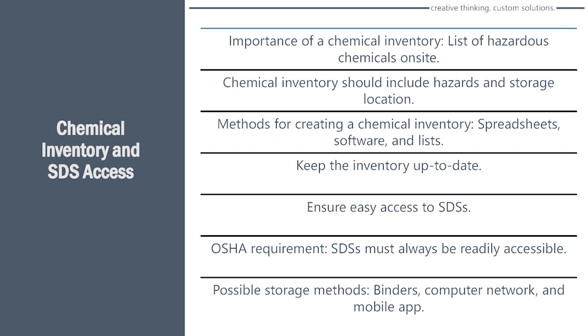Today, you've got all these other tools that are available to you. So your chemical inventory is probably maintained by some kind of existing inventory. And then when purchasing buys a new chemical, they notify someone in EHS, probably electronically, and that automatically gets added to the system. So that's a great way to manage that, and it allows you to be sure you've got what you need. The chemical inventory should include the hazards and the locations of the chemicals, which is the hardest part. I find that when I go to do an assessment at a site and I'm looking for their chemical inventories, they have an inventory of all the chemicals that that plant has, but sometimes they don't know where each one is used, because somebody in purchasing may be maintaining that and they don't even know where it's being used. They just know I ordered it and they sent it and it had this SDS with it.